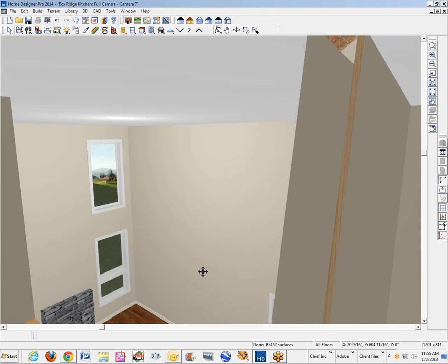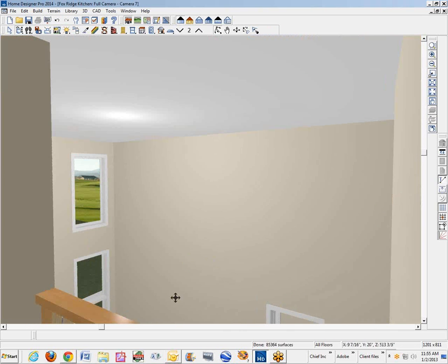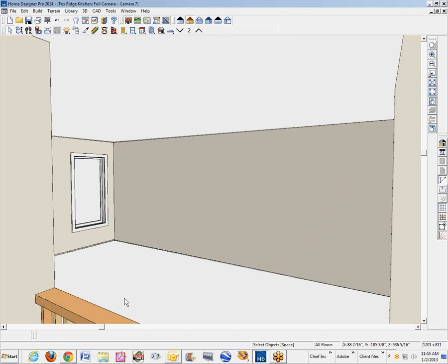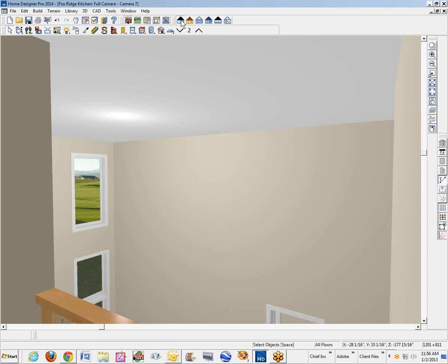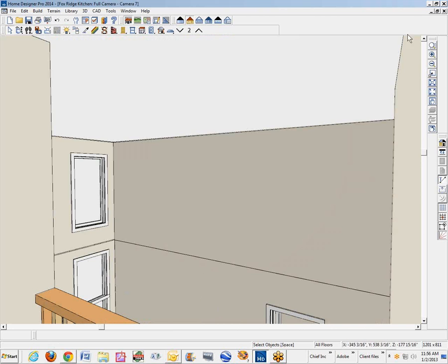I've solved the open below thing by just cheating, basically. I took that material that was coming from the roof system for some reason and used the material painter and got rid of it. Now, in vector views, it's probably still there because opening no material still shows. You'd have to use this tool if you wanted to do a vector view and send it to layout and print it out and just temporarily remove it. My solution only worked in a render camera and not in a vector camera. You have to take an additional step and remove that from the camera view.